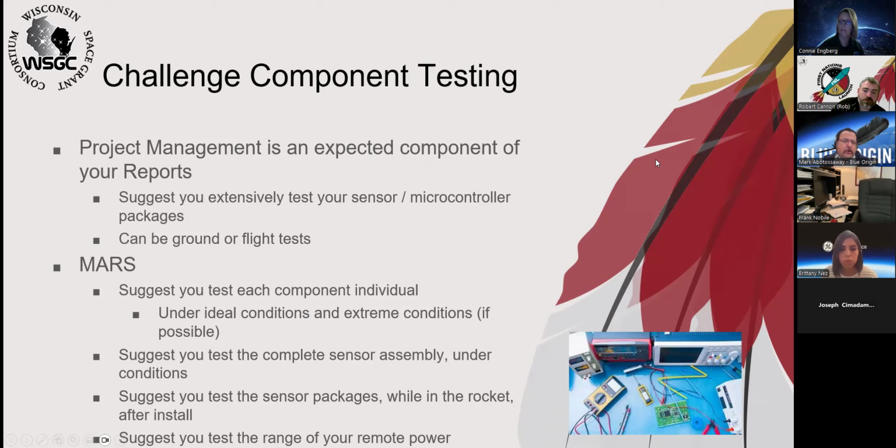And then you could do integration tests, for example, right? It's putting the sensor and the microcontroller into the rocket. It may produce different results when it's inside the rocket, right, as opposed to on the bench. So making sure that your sensor and microcontrollers perform just as well in the rocket as they do outside of the rocket. And understanding if there's any difference or variability between these two. We don't want you to be surprised, you do a bench test at home and you come and do the competition flight and somehow the results don't make sense. So maybe it has something to do with the rocket itself.